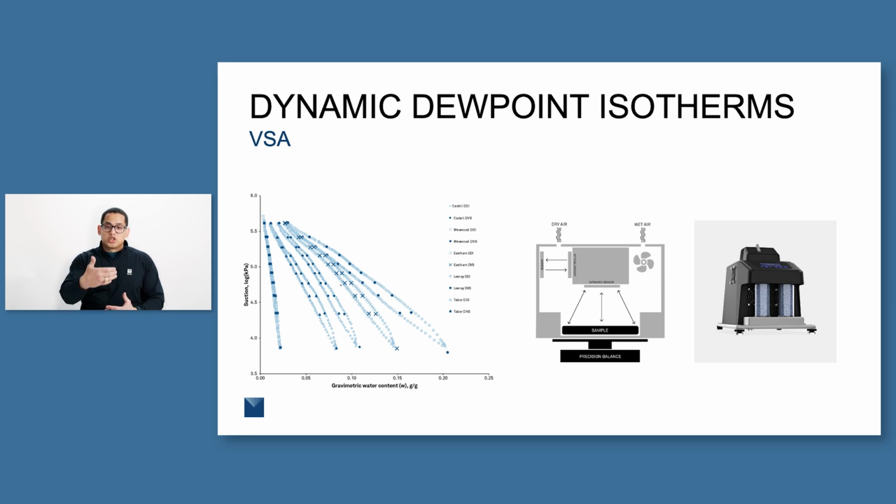So we can do drying and wetting curves with this measurement automatically and generate soil moisture release curves that look like what we're seeing here on the left. And what's really neat about this is it gives us so much more detail about the drying of the soil moisture release curve that we've never seen before. And it's helping us answer a lot of questions about soil properties that we've never been able to answer before.